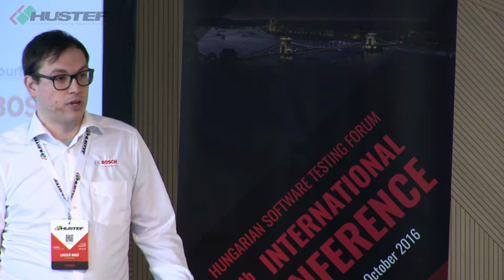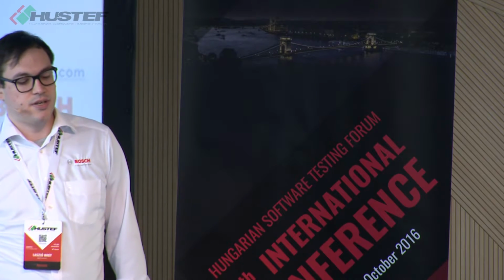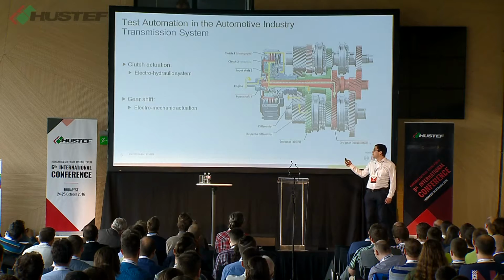If we put the proper gears into position, then we can select the proper speed and the proper torque and speed ratio to the output. And in this particular solution, we have two actuation systems, one for the clutch, which we have to control, and one to move the gears into position. That would be an electromagnetic solution in this gearbox.